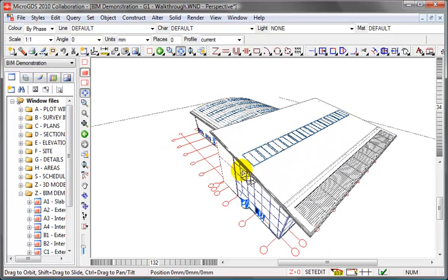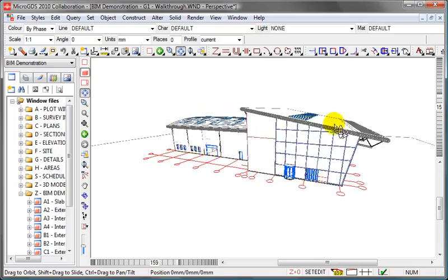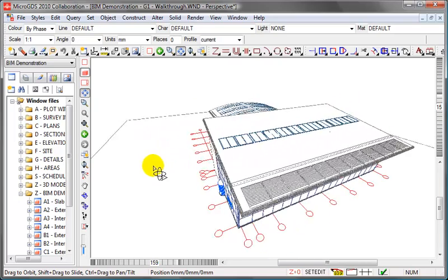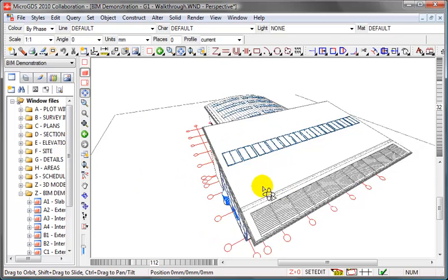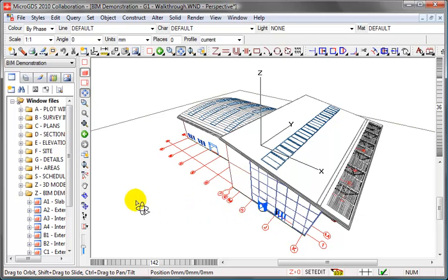And when you use the orbit tool, the point of interest, the look at point as it's called, remains constant, and the distance of your eye from the model remains constant. You're in effect actually moving the eye around a sphere that surrounds the model. Your point of interest can be changed, and we'll look at that shortly, and you'll see how you can actually orbit around any individual element of the model.